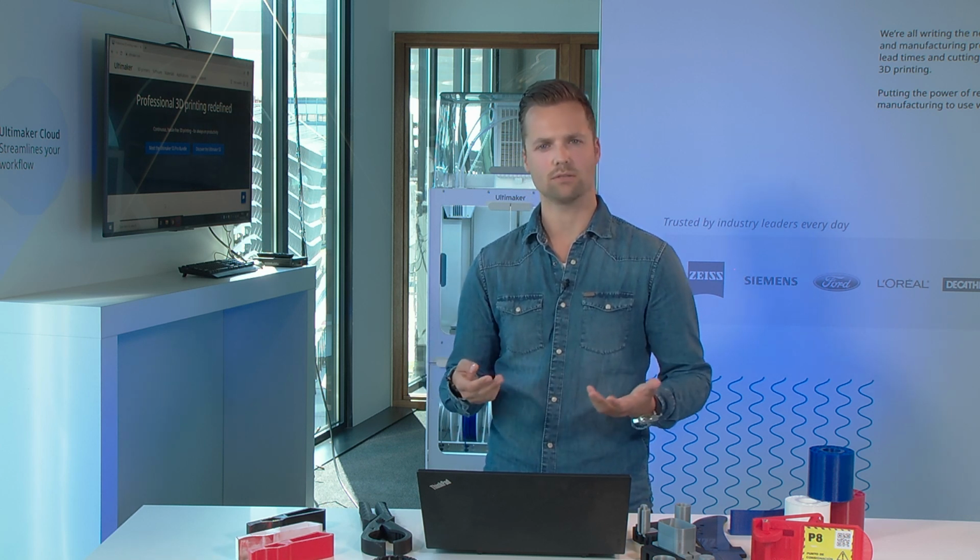So what you can do for tolerances, for example, if you already know I need really a press fit, an intermediate fit or a loose fit, you can either already implement this in a CAD drawing to take an extra offset, or you can also do it in Ultimaker Cura, what I personally use. For example, now we have the intent-based profiles in Cura, where you can select the engineering profiles. These are pre-configured profile settings to also optimize for these kinds of fittings for 3D printing your applications.